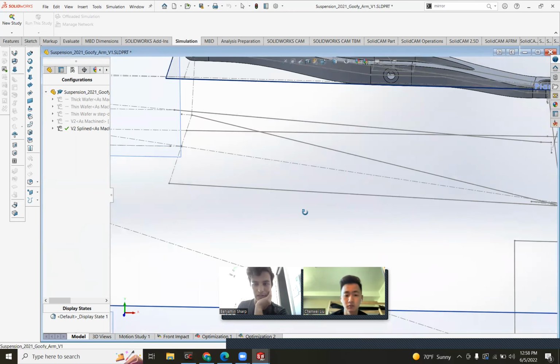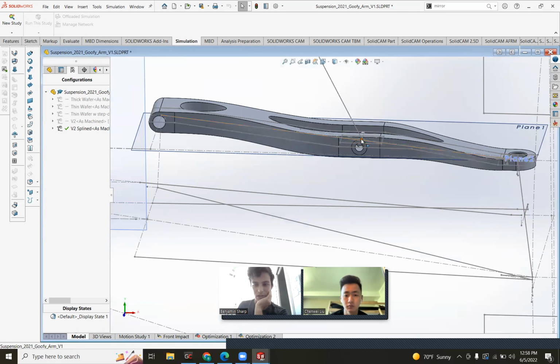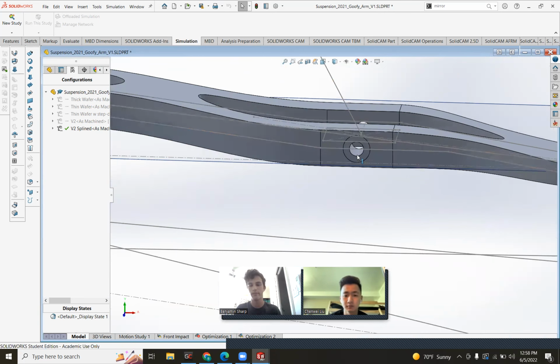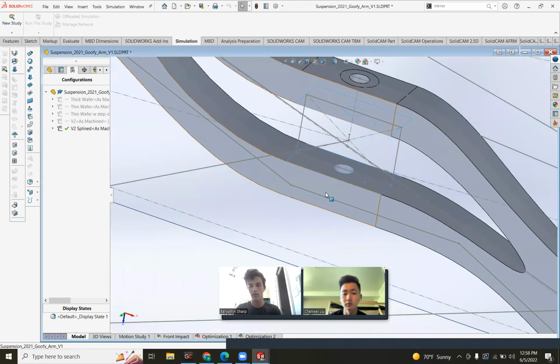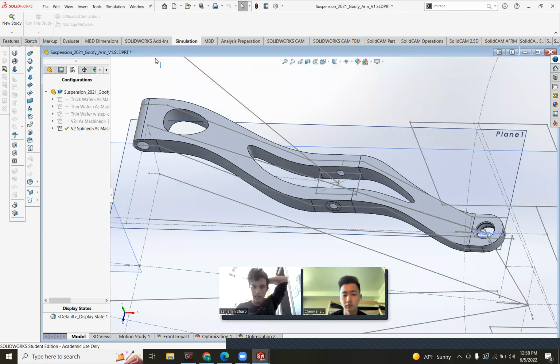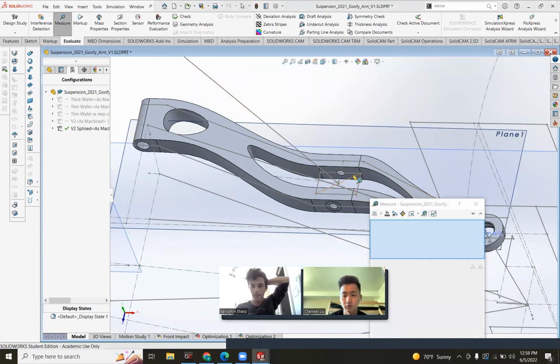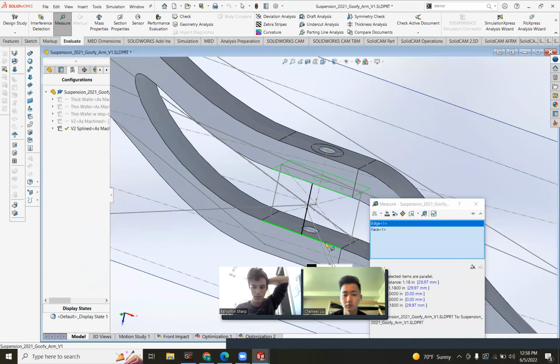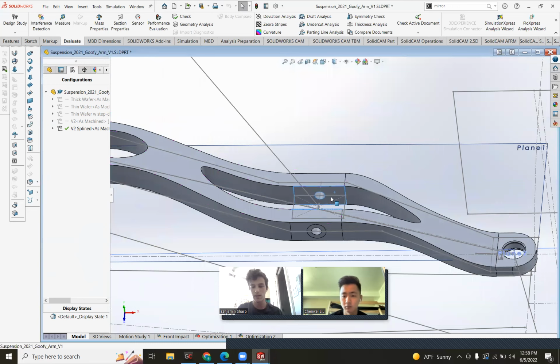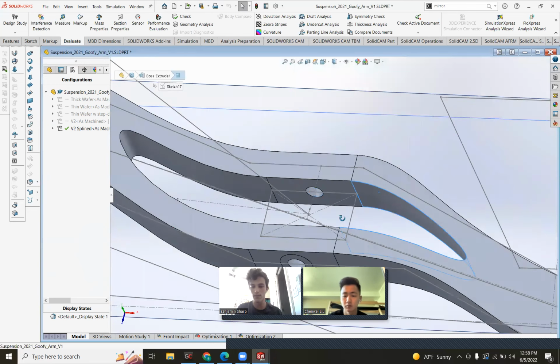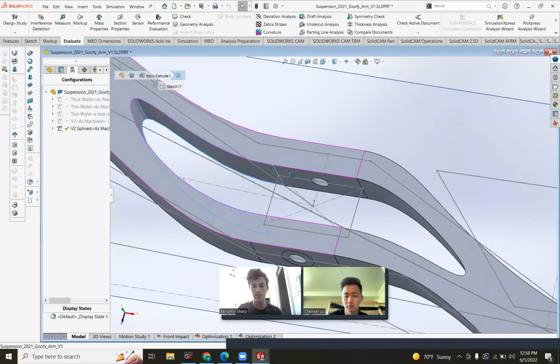Other things, this shock geometry is the same as in the front, where the length here is the shock lever arm, shock moment arm. You have to make sure the shock doesn't interfere with these walls, so they have to be at least 1.18 inches apart. That's the dimension, and that's written down somewhere, and you can also just ask me, but 1.18 inches. You also have to make sure the shock doesn't run into this wall or this wall when it pivots.